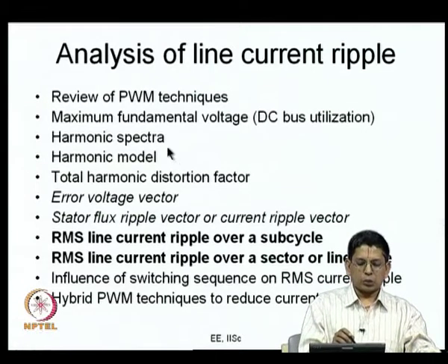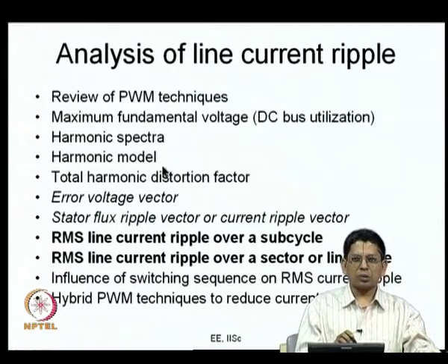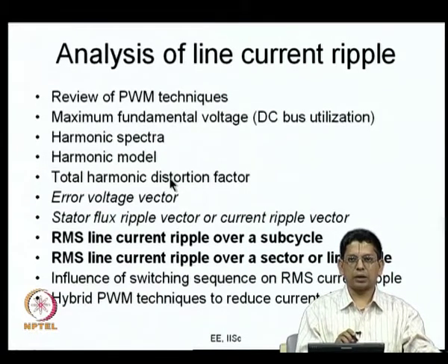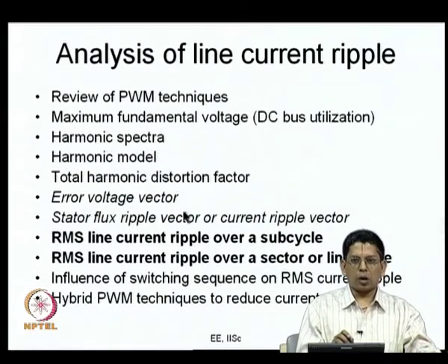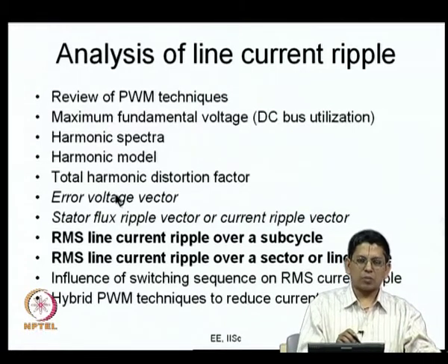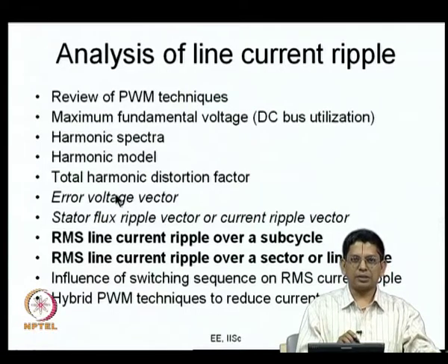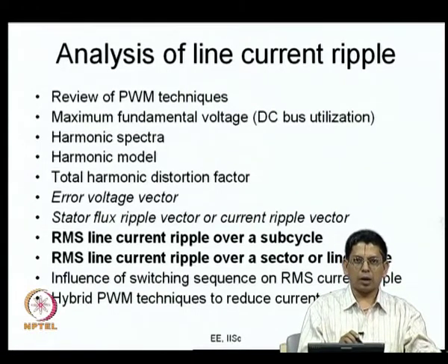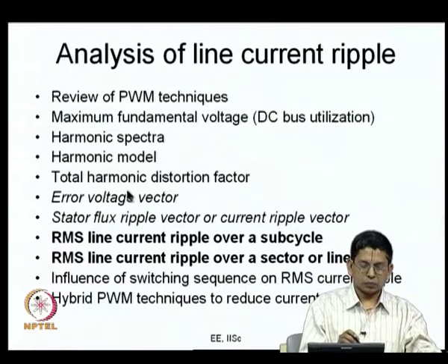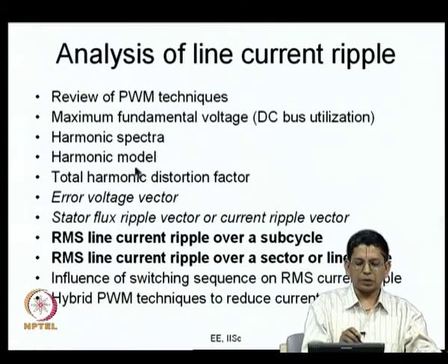And as I told you, our focus is not so much on the harmonic spectra, and I also gave you some references where the harmonic spectra are discussed in much greater detail. And we looked at the harmonic model and the total harmonic distortion factor, etc. And the harmonic model, as you can quickly recollect, is that for an induction motor drive, the harmonic voltage sees the induction motor as its leakage inductance. So, that is the harmonic model. And then this is a measure of the waveform quality.